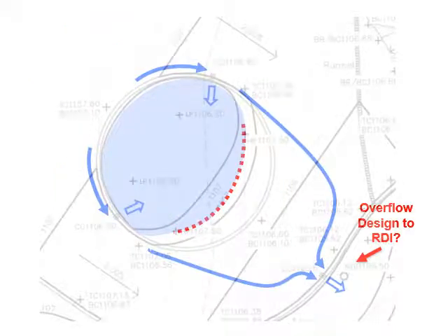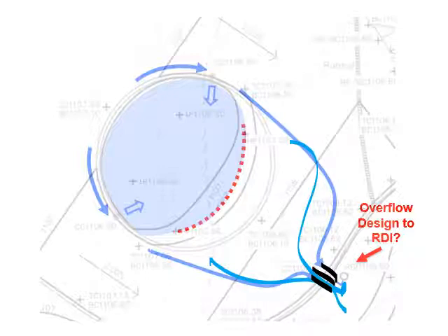So this actually makes a very simple system because we have another curb cut down here. So all that water can simply come through that curb cut. And just like some other curb cuts, you've got a raised drop inlet right after that curb cut. So again, the whole system functions, and there is no need to have an RDI in the turnaround. Your RDI can simply be down here at the bottom of your system.